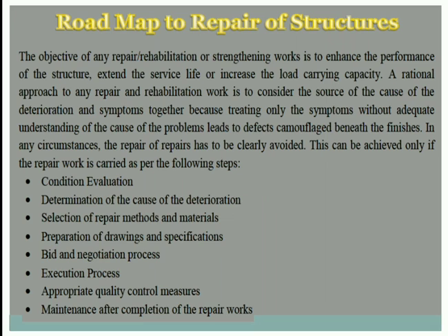Initially, a proper evaluation or survey of the structure has to be carried out by an expert, and all the areas wherein the repair is required have to be noted down. Then the causes of this deterioration also have to be recognized, because the best solution comes from directly hitting or killing the cause.